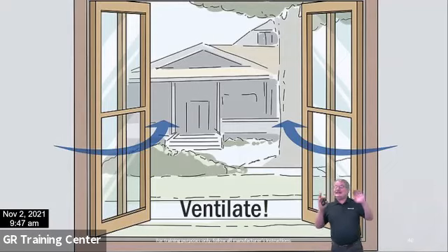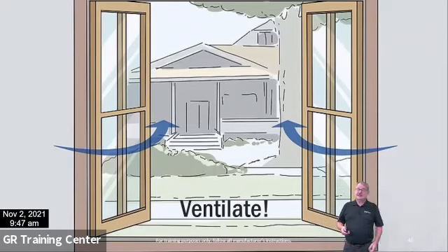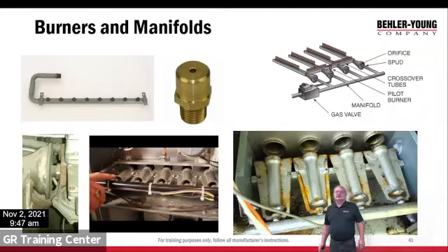We need to ventilate. And if we're above the explosive limit, we don't want to ventilate with electric fans, right? Because if we have too much, we're above the explosive limit. When we start letting air in, we're going to drop it below the explosive limit, and the motor in a fan, the switch on a light could ignite it. So again, something to be careful of. Not to be afraid of, just need to understand, right? We need to know how to handle it.